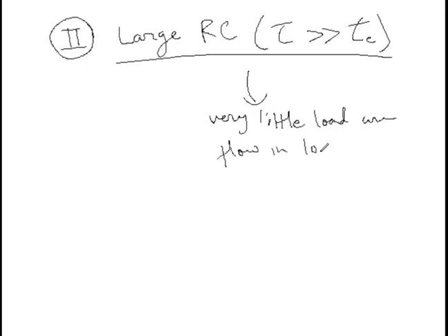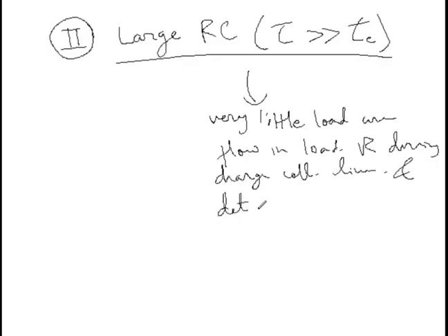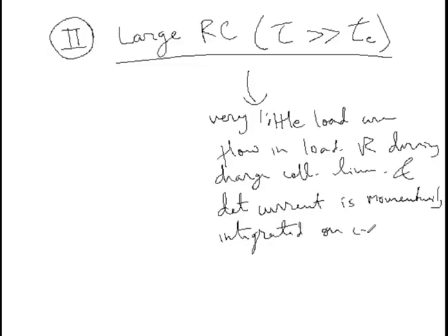Here very little load current flows in load resistance R during the charge collection time, and the detector current is momentarily integrated on the capacitance.